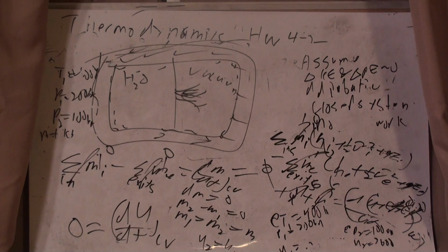So I'm at a case where I know my pressure and I know my energy. I just need to do some interpolation to figure out what temperature is going to correspond to that energy with that pressure. And then same thing with the volume. Once I've done the interpolation for the temperature, I can do the interpolation for the volume, and then just multiply it by 1 kilogram, and I'd get my volume in that case. So pretty straightforward.